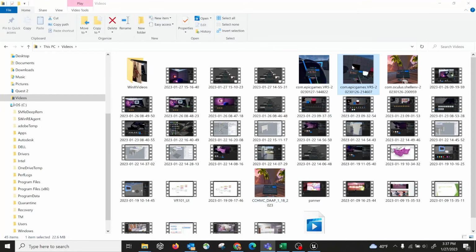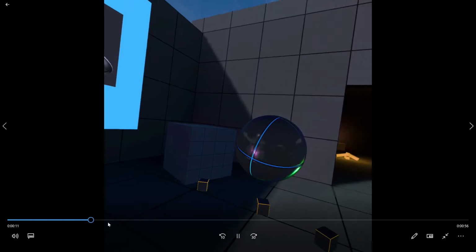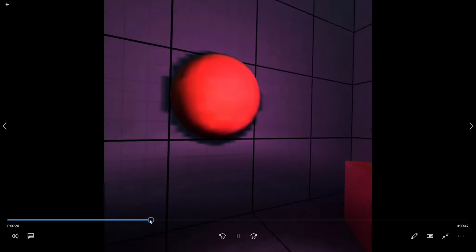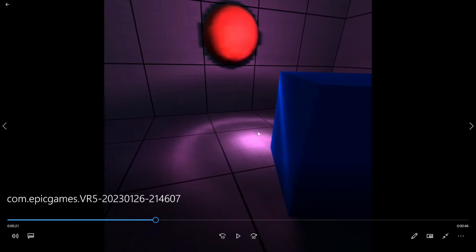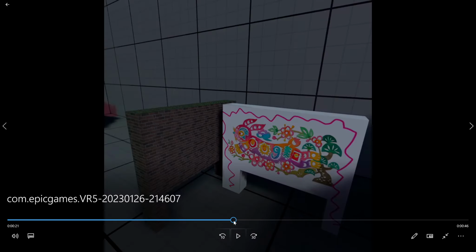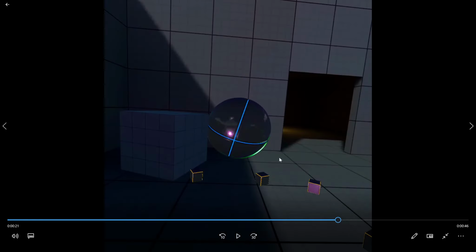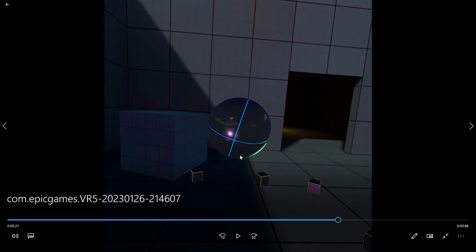So for the second render, I turned on the forward render. And now if I look around, right, you can see this light pattern looks correct. So IES is rendered in the right way. However, there are some issues in this version. You can tell the dynamic objects, the sphere, do not cast a shadow.